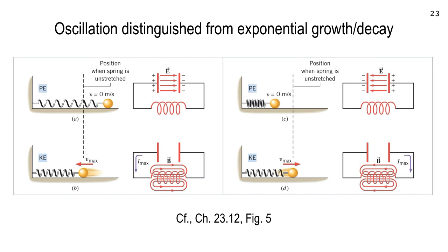Now, we wouldn't say it's kinetic energy in the inductor, but we would call it the kinetic term because it's like a kinetic energy in a spring system. So make a note, this analogy of the spring system with an LC circuit is exact. It's an exact analogy, and it's a very serious one for us.